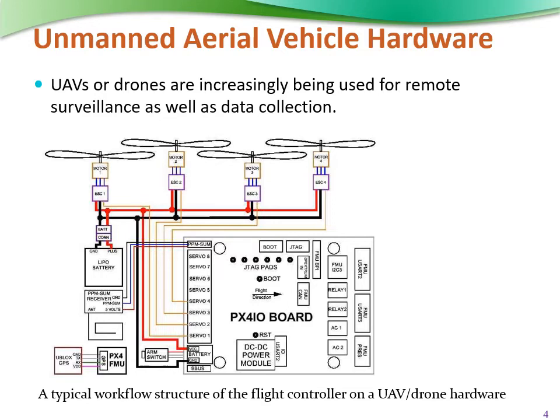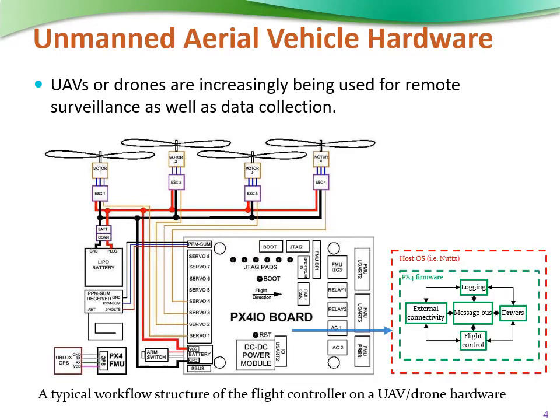It includes drivers for different types of sensors, sensor fusion algorithms, feedback control algorithms, and many other things. This PX4 firmware runs on a host operating system, and this operating system provides a message bus that handles the communication between different components of the firmware: flight controllers, drivers, external connectivity, and also data logging.